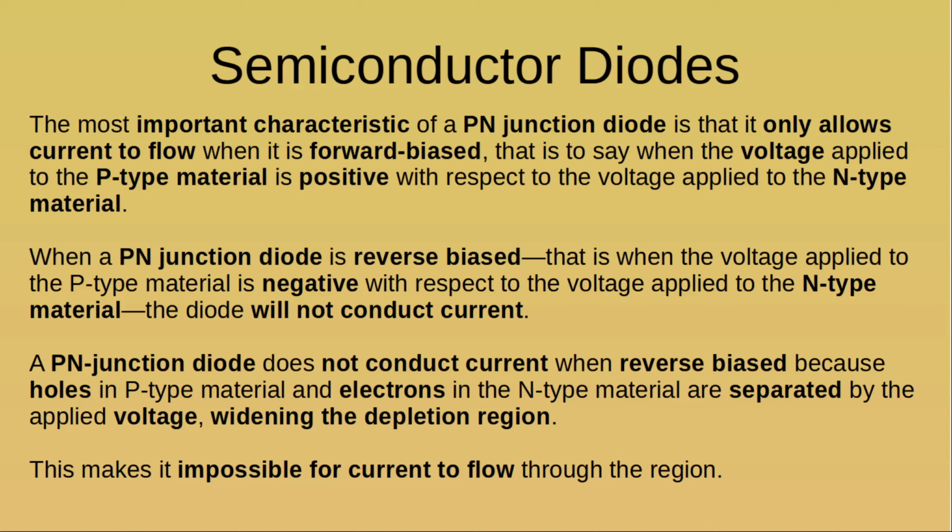So when we talk about a varactor, that's how it works: by reverse bias and changing the width of the depletion region, which varies the capacitance. So it becomes a voltage controlled capacitor. It turns out all p-n junctions have capacitance due to that depletion region, which is one of the things you have to take into account in circuit design, that intrinsic capacitance.